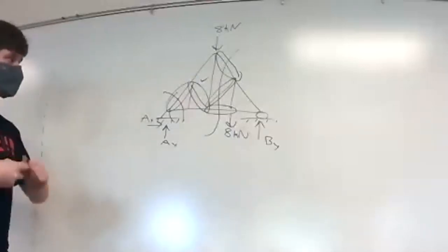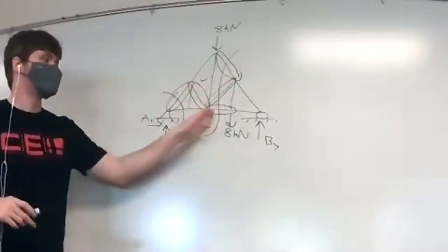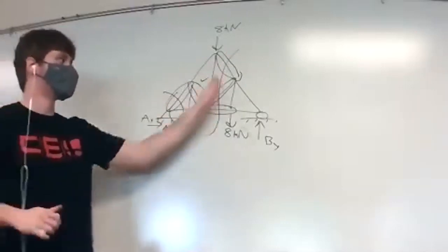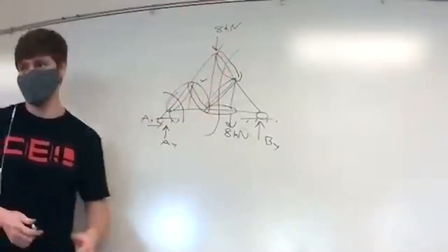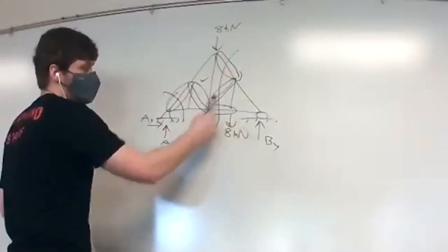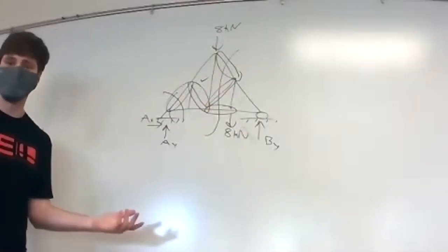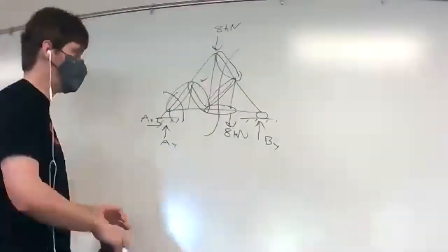For a multi-layer truss, it's always best to make a cut instead of using method of joints. When you have multiple members like this, back to back, yes, you can do method of sections because it will be much faster, as opposed to going from this joint to this joint to that joint to this joint. Moving around like that takes way longer than you guys are going to have time for.